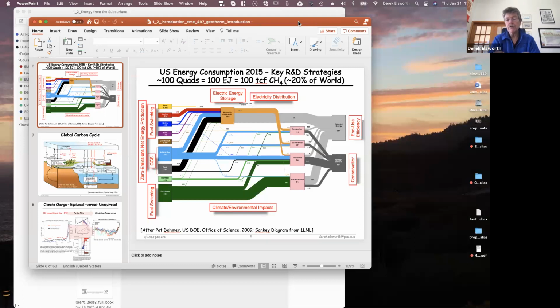And of course, you probably realize that you don't actually have to get above 100 degrees centigrade to generate power from water. You don't need to necessarily flash the water to steam. What you can do is transfer the hot water into a binary agent such as IPA, isopropyl alcohol, which has a boiling point of 38 centigrade. You can flash the alcohol to steam, use that in a closed loop system to run a turbine, and then you can recondense it, and then you can use it.